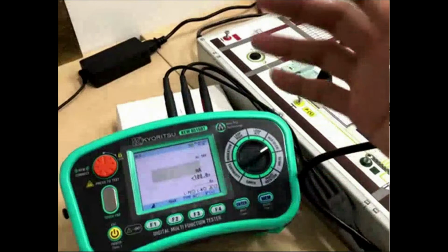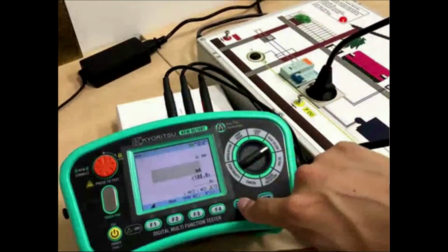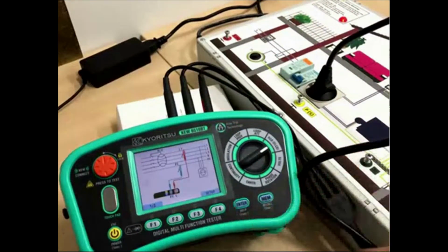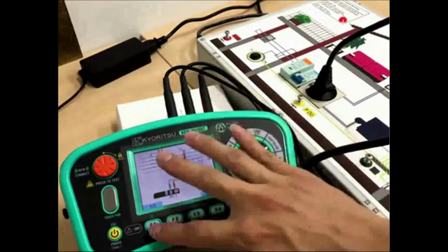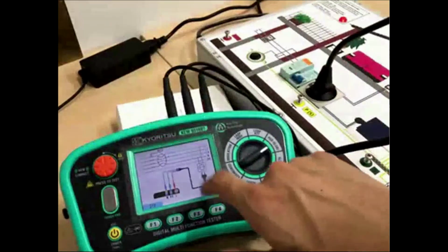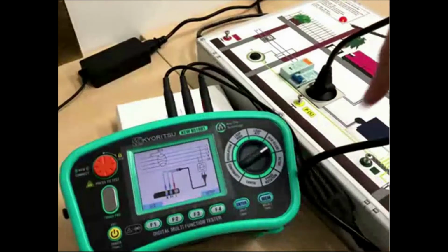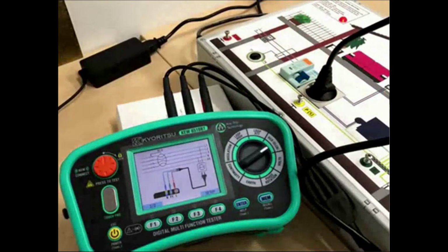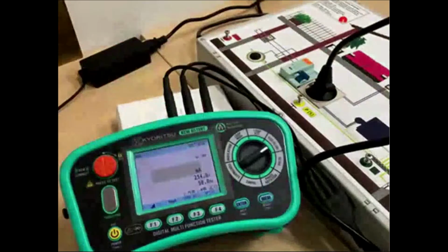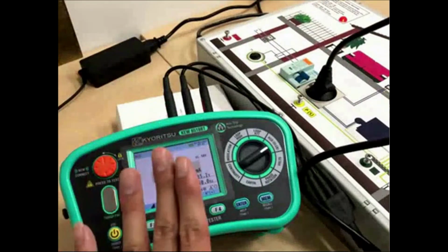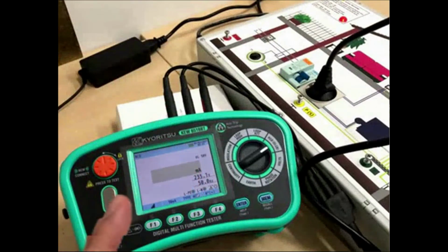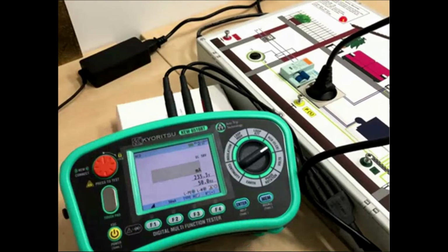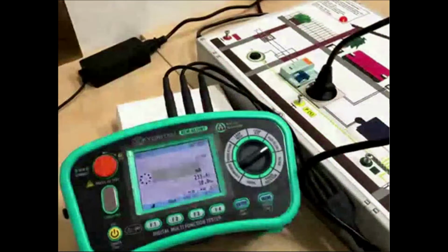Okay, now how to test? You don't know how to test, right? Press help key. Okay, this one I cannot show you. This one is very dangerous. We use this test probe, same as the test probe shown here. Okay, now we turn on our RCD. Step one backward. We want to see what is the tripping current. Our rating current is 30 milliamp, but our tripping current must be lower than this. Okay, press.